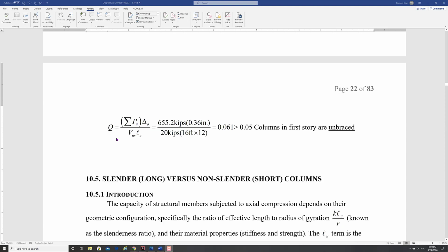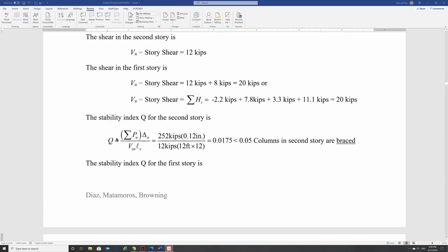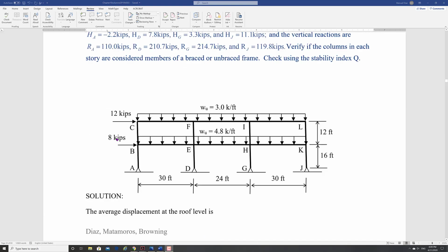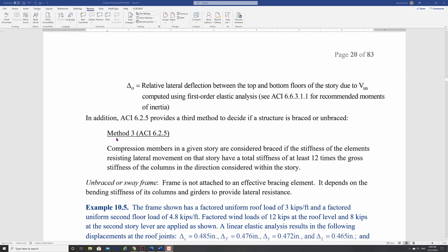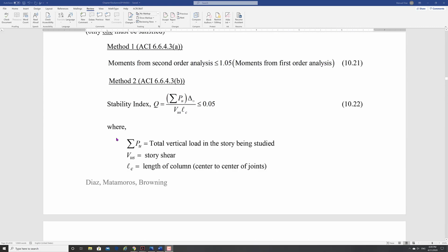And this is something that is important because otherwise your bars that are in compression could buckle and push the concrete, so the shell of the concrete, the outside shell, they can push it out.